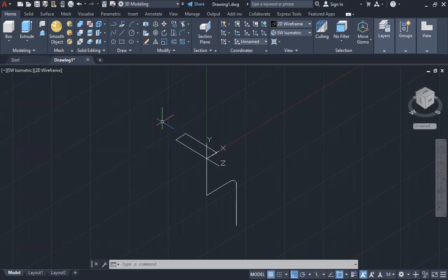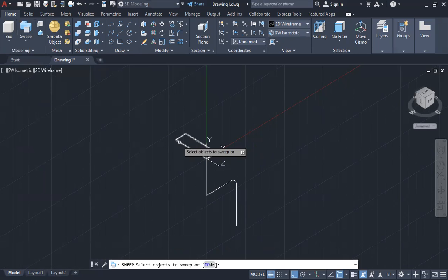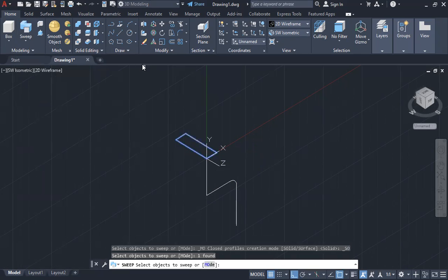Set, Sam? Alrighty. Now we're going to sweep this surface through this path. So if you come up here to where the extrude is, click on that, you've got your four different tools. We'll select sweep. We'll then select the surface first because it says the objects to sweep. So the object to sweep is the surface. We'll click on that, press enter, and then we'll select the path.